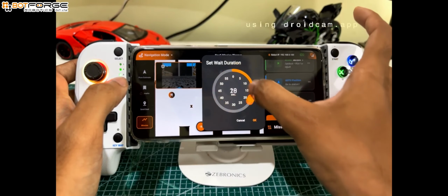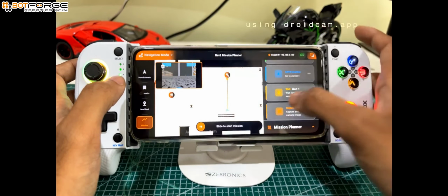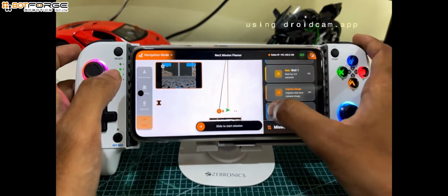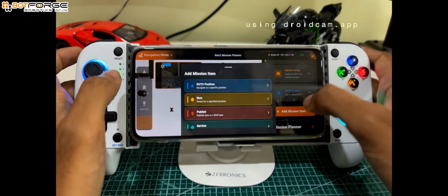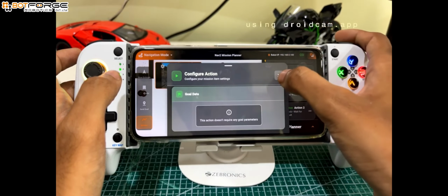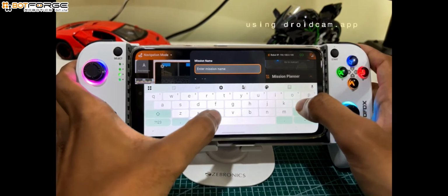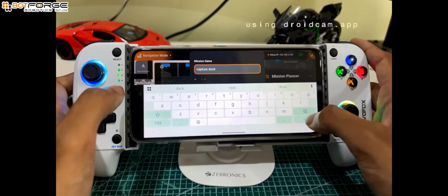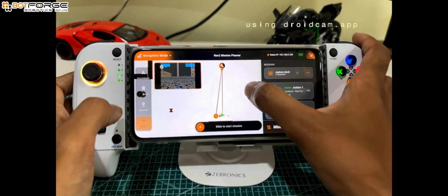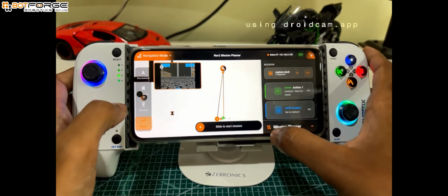Click again and select Time. Next, add Capture Image. Next, select Go to Position. Finally, add Action for Dock with Wait for Result enabled. You can save this mission for reuse. It will be saved only for this map. Then slide right to start the mission.